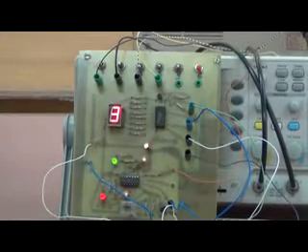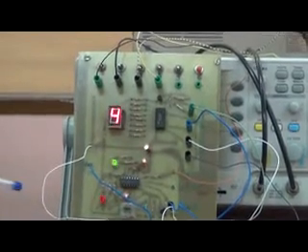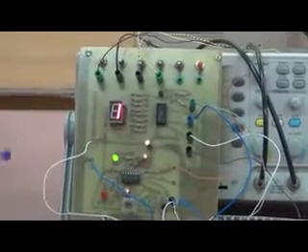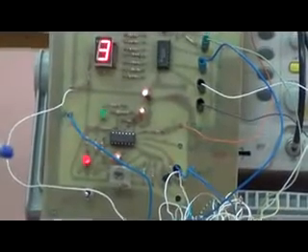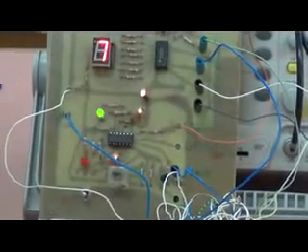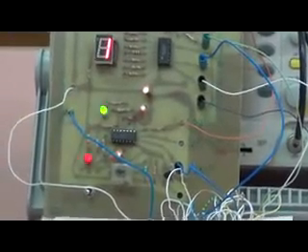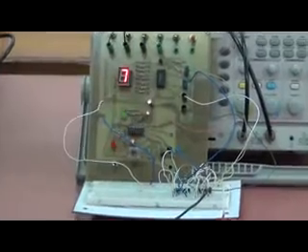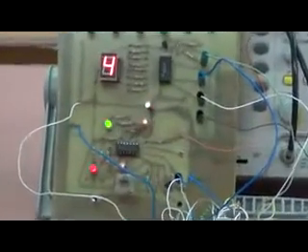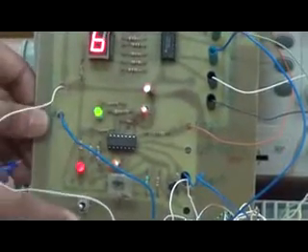Currently the clock can be put into auto mode as well as manual mode. Currently this is in auto mode, that is, the counter is getting the clock automatically from this digital test board, which drives the flip-flops, which generate the output. We can also give a manually driven clock to the flip-flops, so that we can observe the values of the counter manually. Now I'll put it into manual mode.